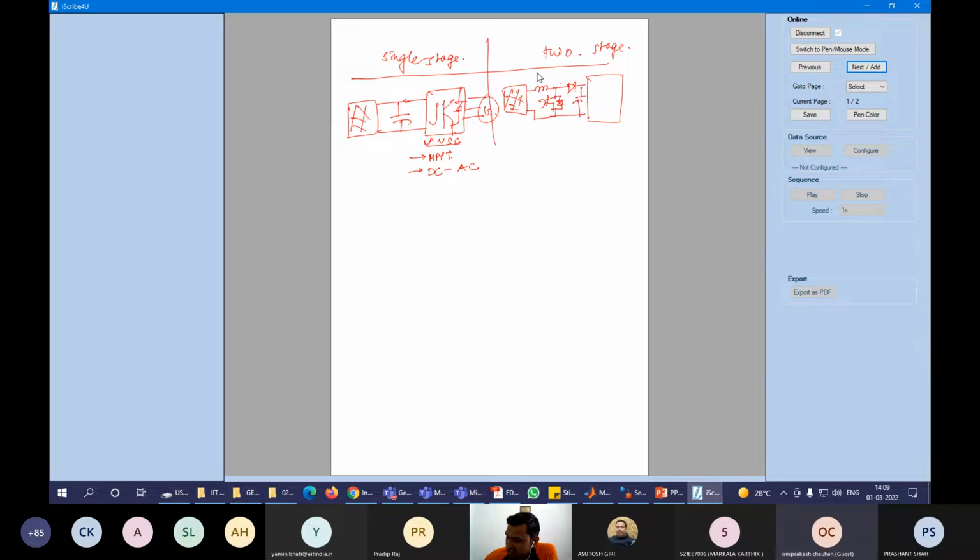And then we are having a DC link capacitor, and then we are having this VSC, and then this three-phase grid load, all those things. Here we are having a separate unit for MPPT and a separate unit for DC to AC conversion. The multi-mode features like power quality improvement and other features we have taken care of by this VSC, this DC to AC converter.